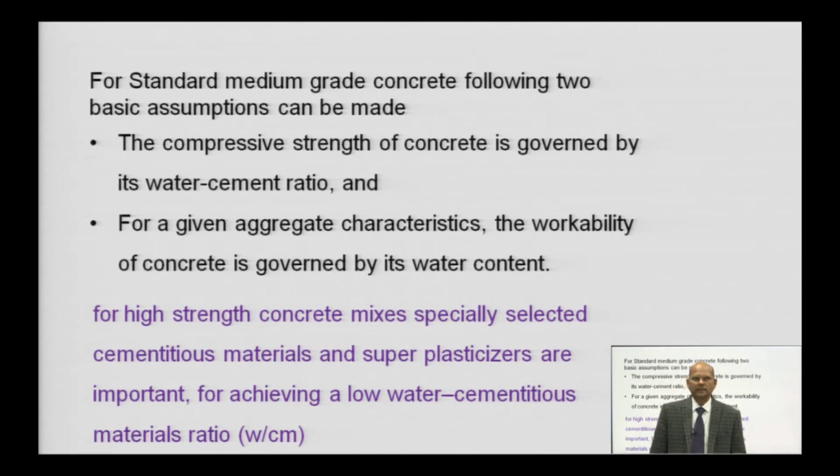So, for a standard medium grade concrete, the following two basic assumptions can be made while we are designing the concrete mix. First, the compressive strength of concrete is governed by the water cement ratio, and second, for given aggregate characteristics, the workability of concrete is governed by its water content. So, how much water is there will decide the workability of the concrete.